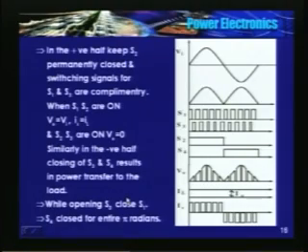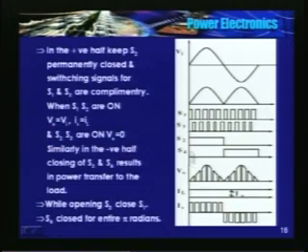How does the source current look like? Same philosophy. I have assumed the current to be constant and ripple free. So when S1, S2 on, load current is same as the source current, and during the freewheeling period source current is 0.